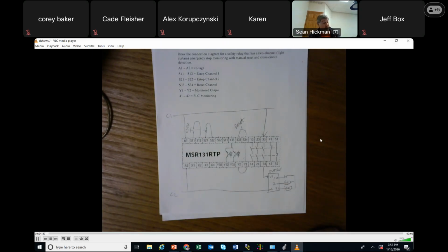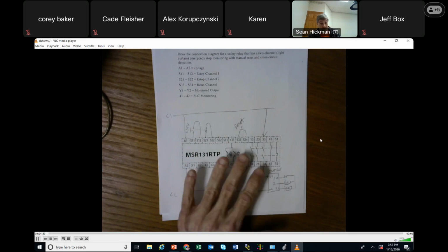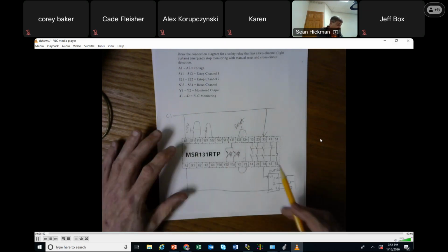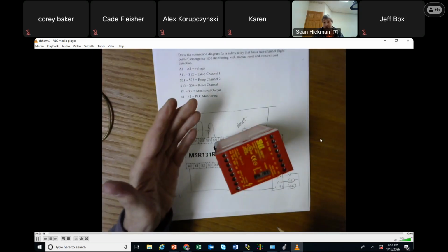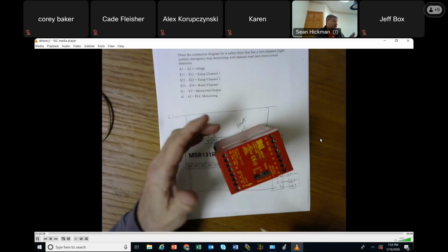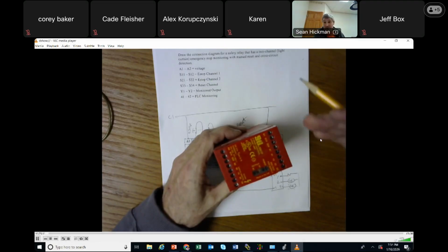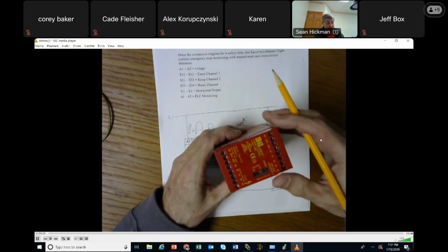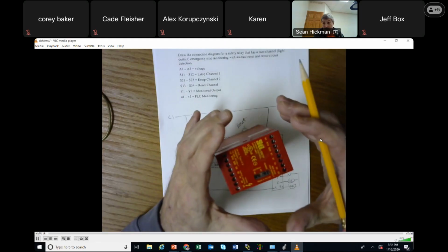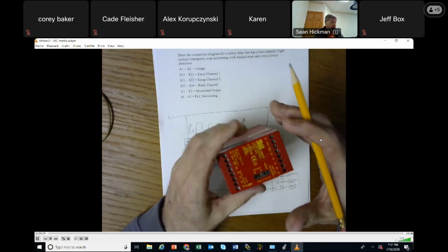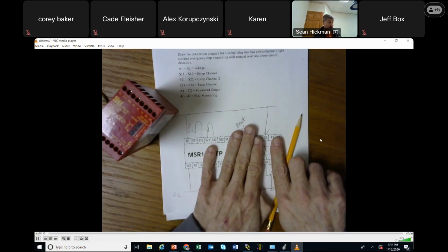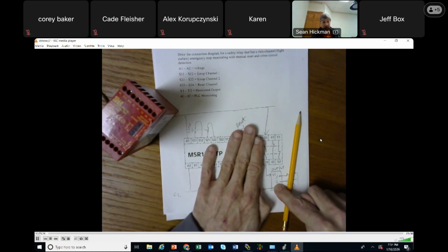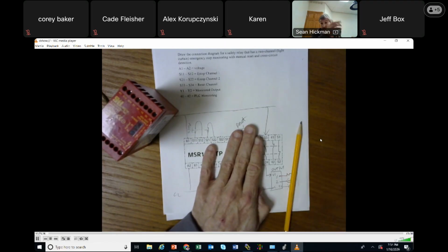All right. So, and remember, this is just this safety relay. This 2-hand could do the same. There's all kinds of different safety features that can get programmed into a safety relay, the functionality of a safety relay, that really just closes 2 contacts, 33 and 34, that gives voltage to a contact, or gives voltage to an output card, or gives voltage to a robot, or anything.